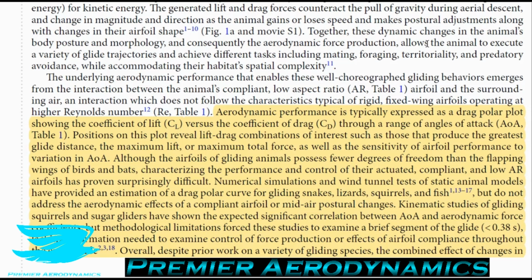So wingtip vortices push the air down, and this means that the effective angle of attack, the angle of attack that the wings actually see, is lower. So what this means is you can push the wing to a higher angle of attack, geometrically speaking, and still keep the flow attached because the flow is being pushed down. And that means the effective angle of attack is lower.